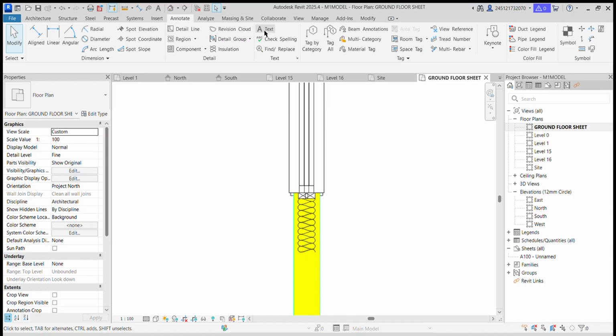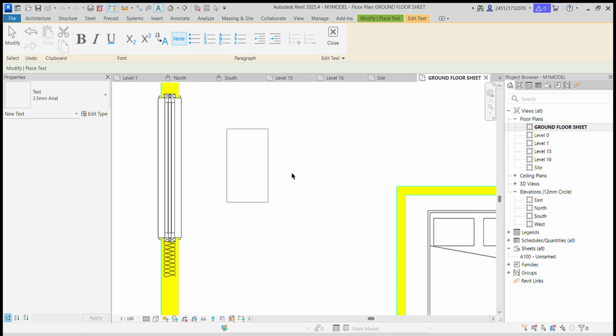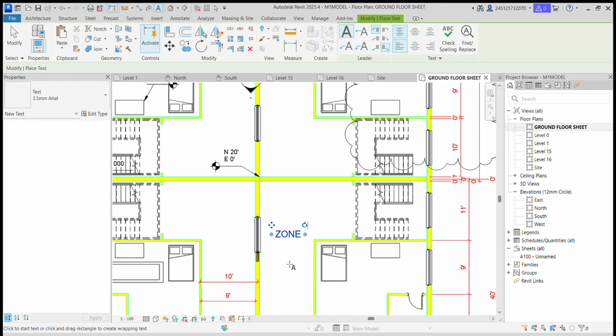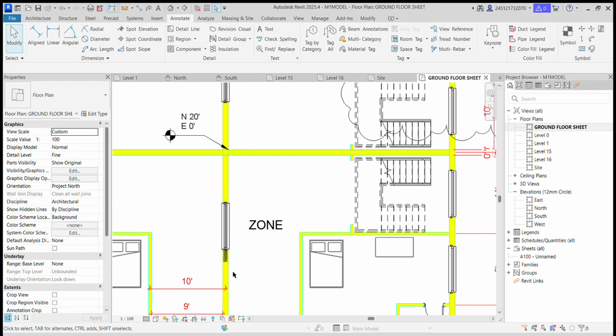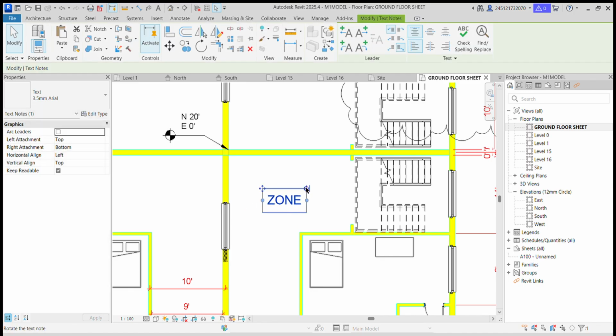Okay, so here we go to the text element. Next note down text, TX. If you want to draw text now, you can choose text. I want to draw text here. Zone 1, you can use the command for text creation. Okay, so this is the key. If you want to control the sizes, how to change the sizes? Once you select it, everything will be available in properties itself. Okay, select the properties, you can change.